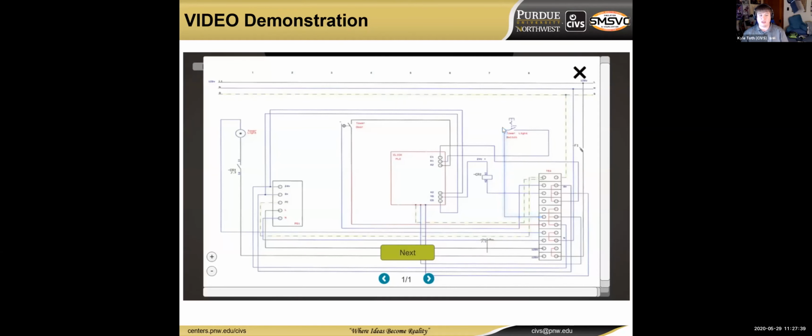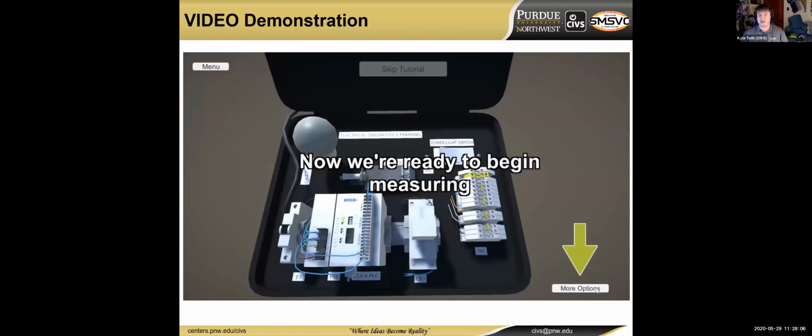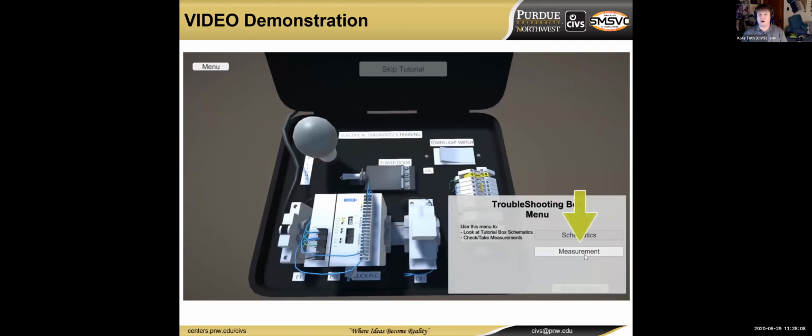So we start looking at where the tower light switch is, and we want to actually check to see right there. We can see, with my mouse here, the wire that goes to the front end of the tower light switch, the input side of it. We trace it back to where that goes onto the terminal block, and we want to see if there's actually voltage there. And ordinarily, if there's no voltage there, then we continue checking to see where we're not getting power.